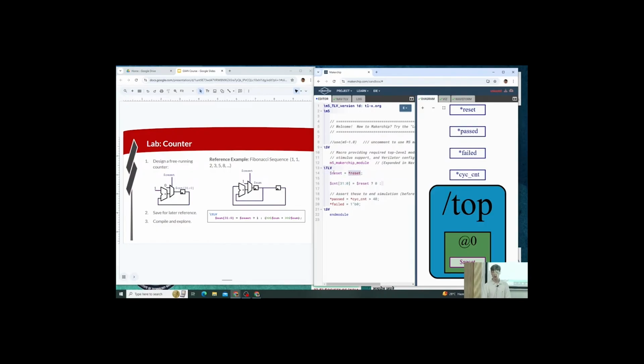So you're really just sort of putting that reset in a TL-Verilog namespace. It's notation for in TL-Verilog context. That's your notation for a SystemVerilog signal. In TL-Verilog context, you would use a star. So, you know, here in Verilog context, you can just reference it as reset.